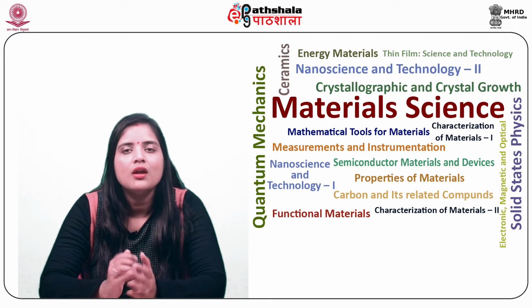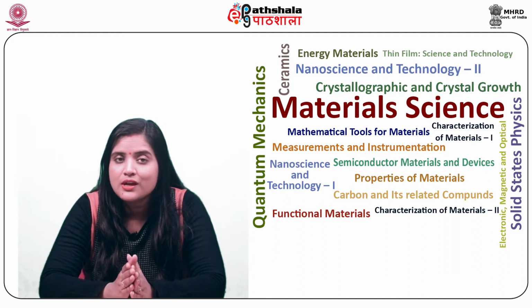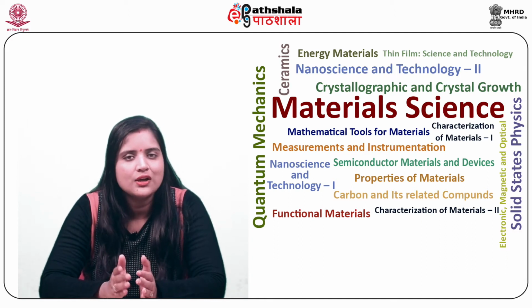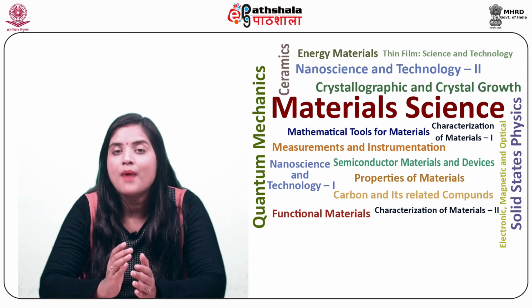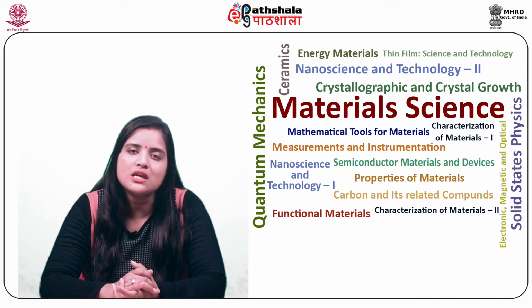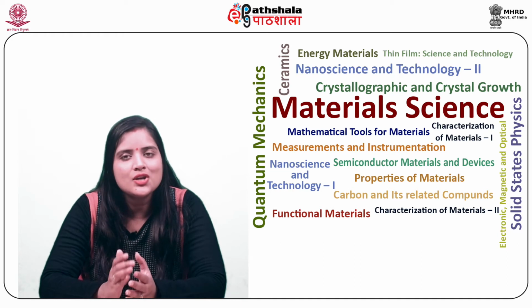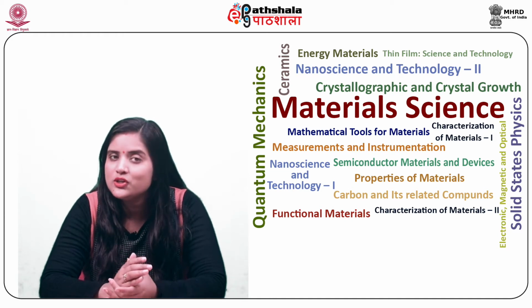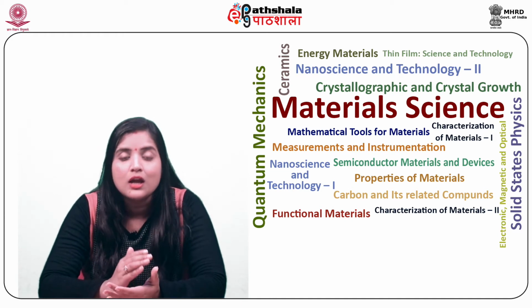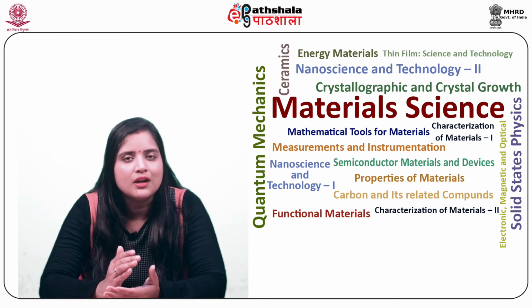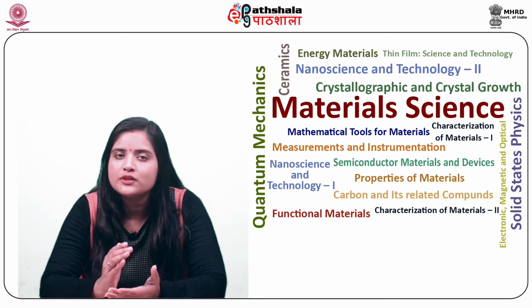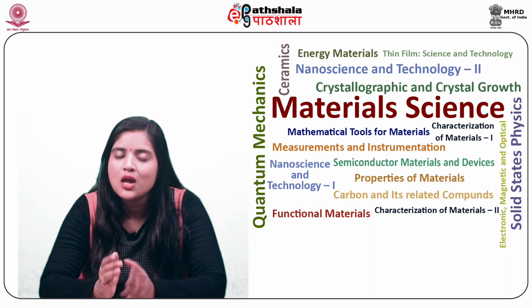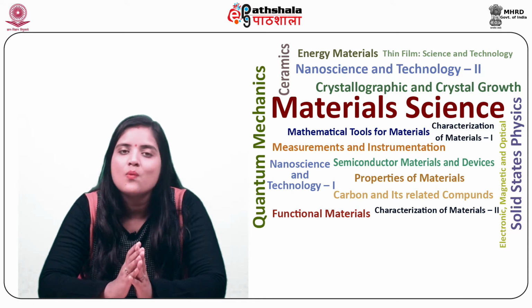capacitor. Differential capacitance is more significant, which is defined by the equation C equals dQt by dVg, and it determines the rate of change of the total charge density with respect to voltage.